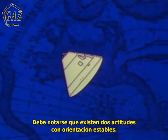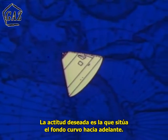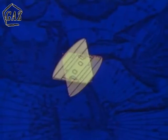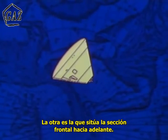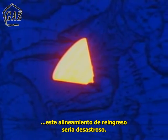It should be noted that there are two stable trim attitudes. The desired one is blunt end forward. The other is with the small end forward. Since the heat shield is on the blunt end, this entry alignment would be disastrous.